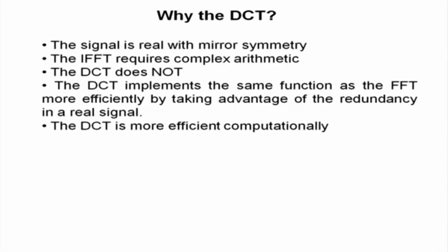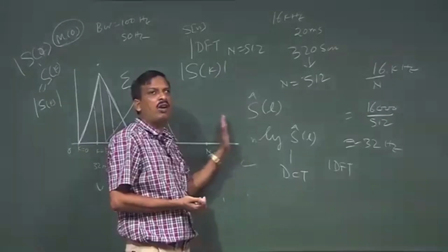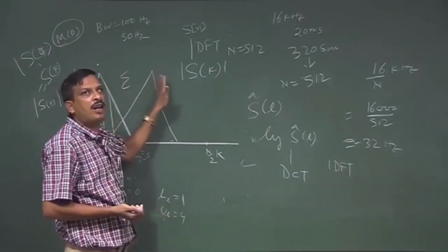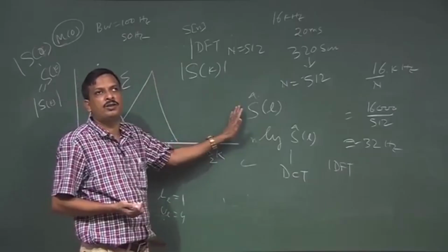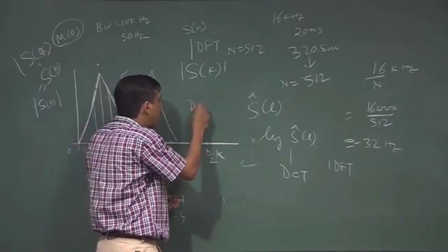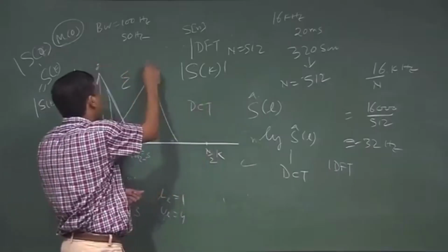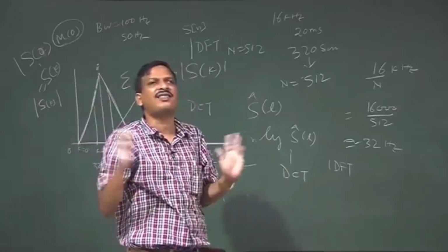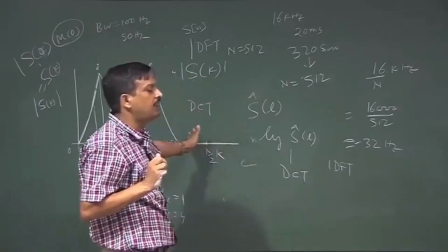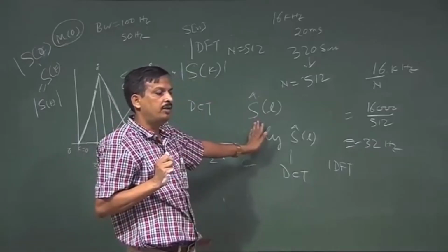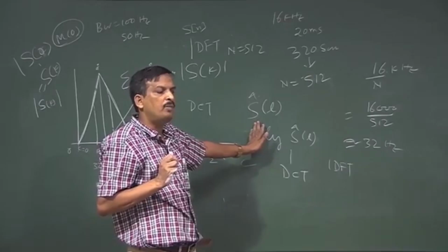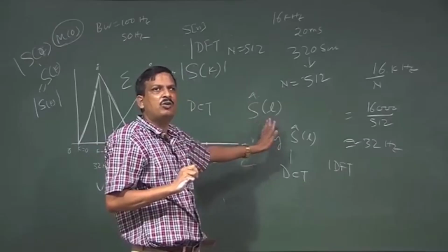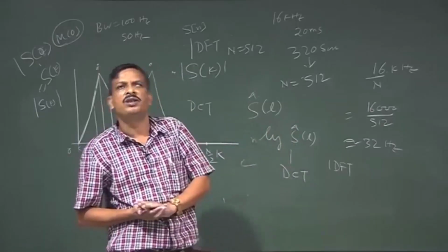The DCT is required to decorrelate the extracted cepstral coefficients. So, I use DCT to decorrelate this filter output. That is why I use DCT, and DCT acts like an FFT. Here I have used DCT because FFT is complex, so complex arithmetic is required. But DCT implementation is easy at this stage. That is why instead of FFT we use DCT.